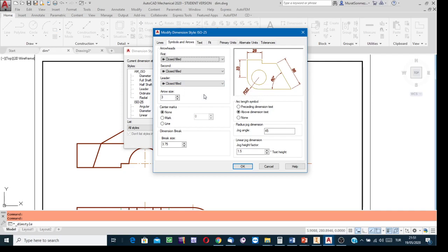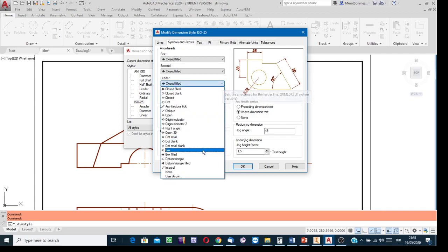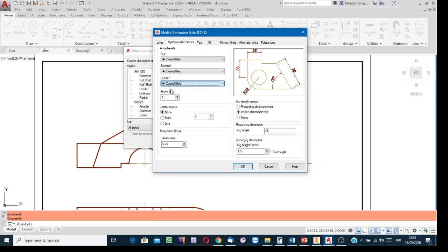Well, leader lines, no matter whether it is engineering drawing or architectural drawing, or whether the standard is ISO or American, quadrant first, quadrant third. It is under common agreement in any branch, in any unit system, in any format of any standard. Well, the leader lines use arrowheads. Okay, so select from this list the close filled option, blackened arrow. The termination symbol arrow size is an isosceles.